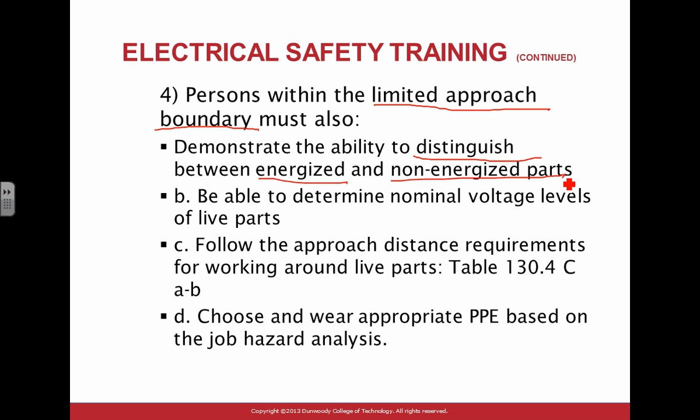So verifying, can you verify that this is dead? What I always tell people is you verify the hot, the neutral, and the ground. You never know how they wired it. When they're all dead, then you've verified. Not just the hot. Well, I verified the hot here, and some electrician flipped it and made the neutral hot. I get a really good zap.